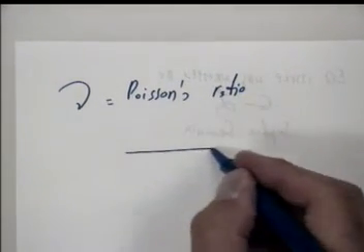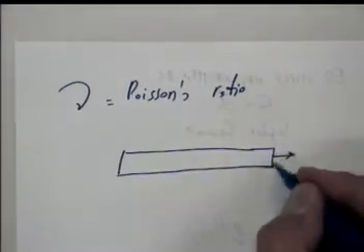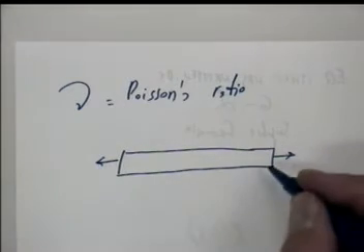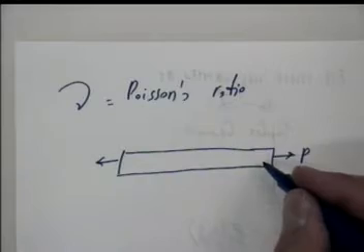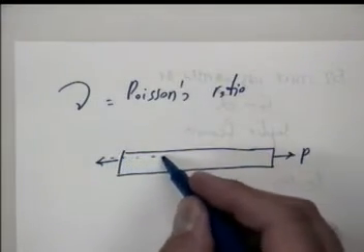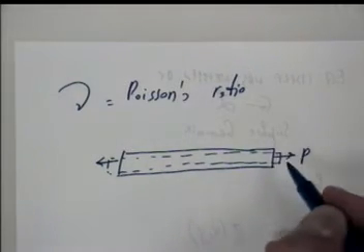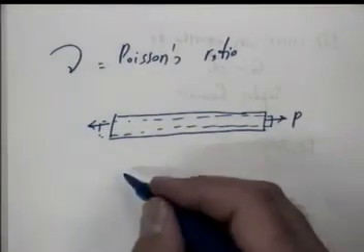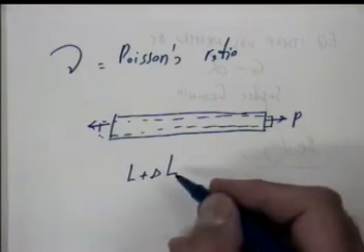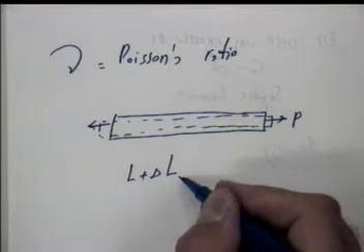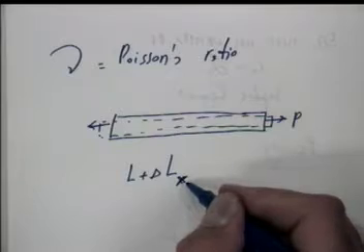Poisson ratio says actually that if I have a strip, for example, and I am causing to this strip to have, so that is a load. This load causes this strip to elongate. So as a result, we will have L plus delta L. Okay? So that we will call it delta Lx. Okay, that is an elongation in x direction.